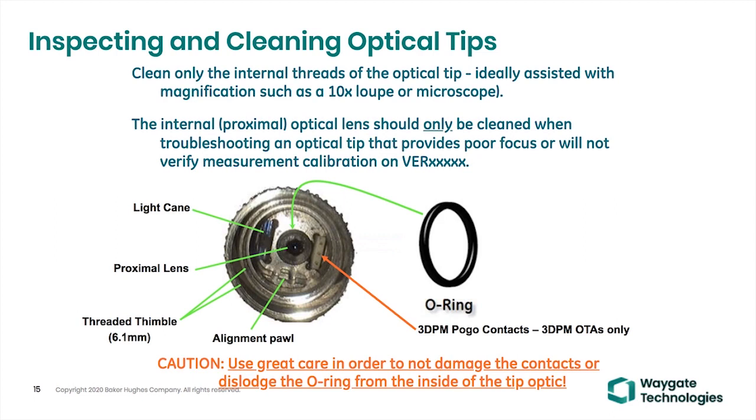Put some water on a shop towel, start at the torsional relief section all the way back at the camera body, and slide your hand down with light pressure. Don't squeeze it, because you'll miss the nuance of any damage or fraying that's on there. And walk your hand along the whole length of that insertion tube.